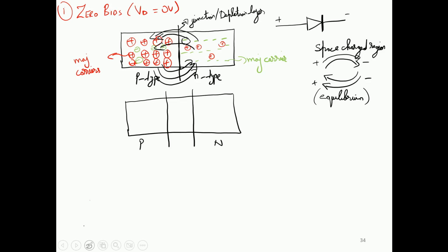So this is basically the depletion layer that gets created. Depletion layer by name means that the electrons and the holes have just done the recombination, and there is no movement of free electrons inside this. That is why we say this is a depletion layer. And sometimes in some of the literature books, this is also known as a potential barrier. It is called a potential barrier because we will shortly see that an electric field gets generated.